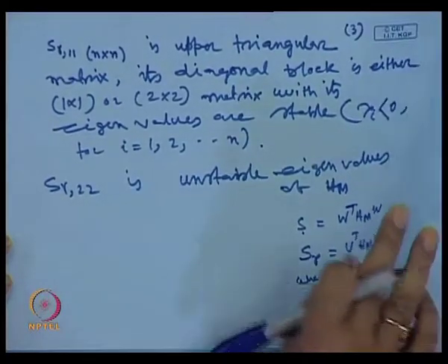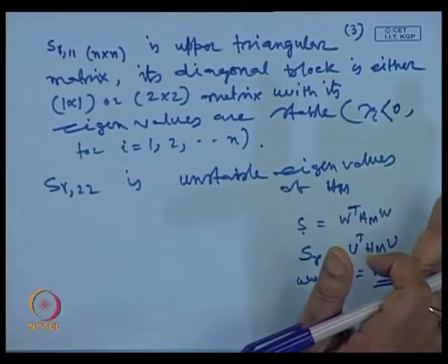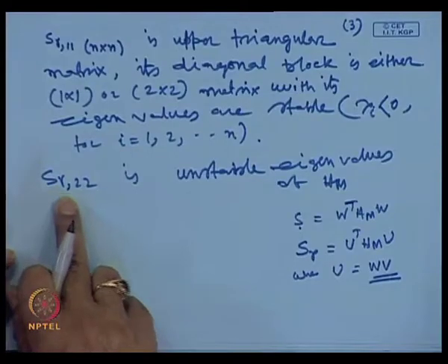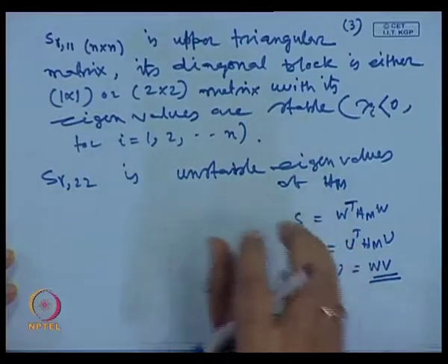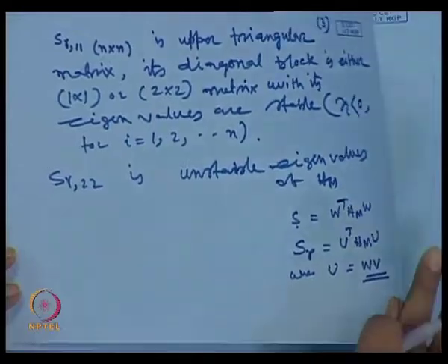So, once we have done this third step, we have converted into the Schur form by reordering. Once again we have reordered only this; that is the only difference from step 2. Step 3 is different from step 2. We have reordered the Schur form matrix, the SR matrix, so that stable eigenvalues come first and next are the unstable eigenvalues.